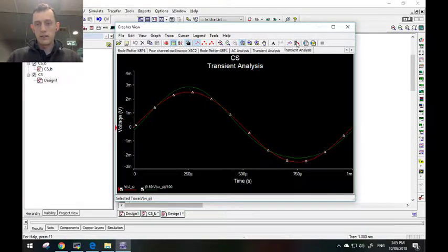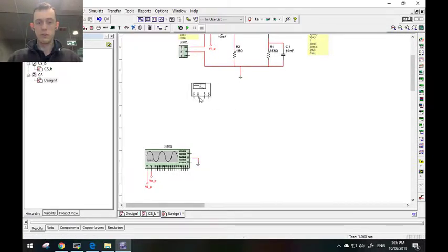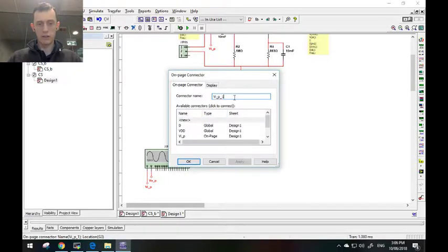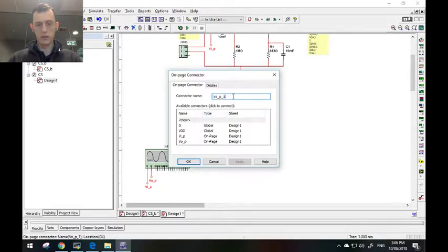The only other thing left to do here, I don't know if there's anything interesting there. No. The only other thing left to do here is to do a Bode plot of the system, and then we did that before, but we'll do it again. Last time it came out with negative 25 decibels, and that's because, believe it or not, this system was not an amplifier. So we're going to use these pins to do the Bode plot. We copied them across, and so it automatically updates the name, which is useless, but it's just how it works. So we just edit those.